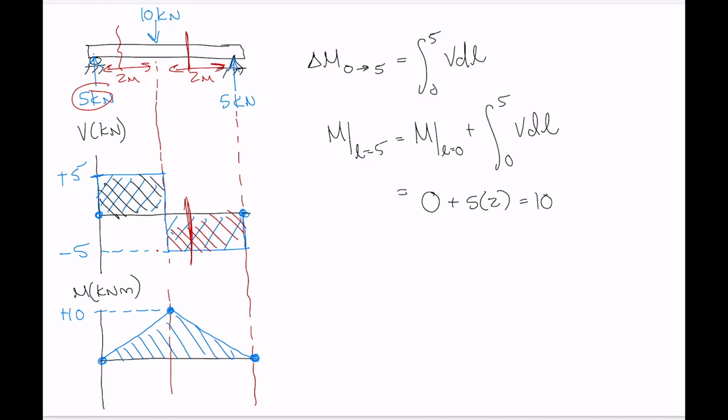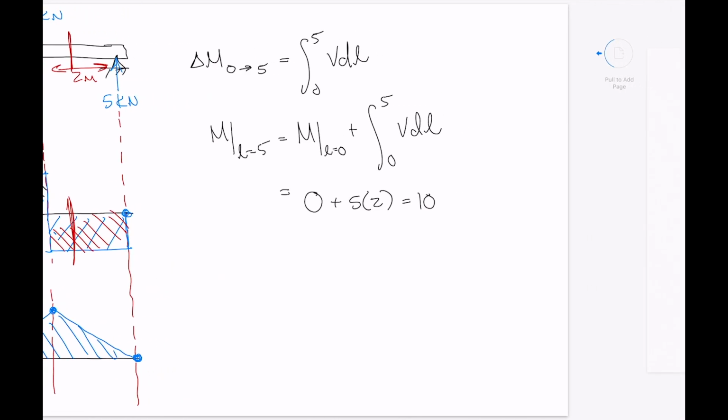So there are shear and moment diagrams using the graphical method, right? Really, really quick, really, really easy. So let's do a second really basic example here. Okay, in this case, let's take a beam that just experiences only a point moment. So let's make this 20 kilonewton meters, and let's put that right in the middle.